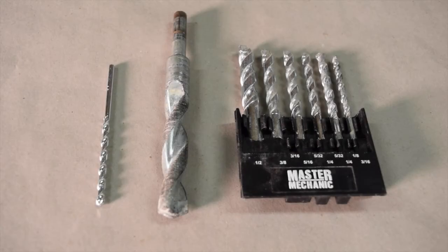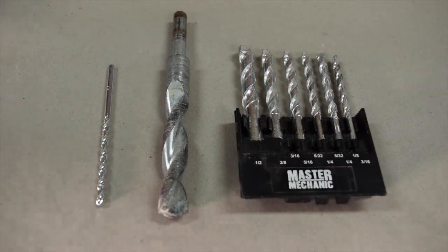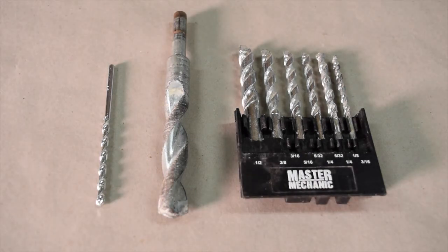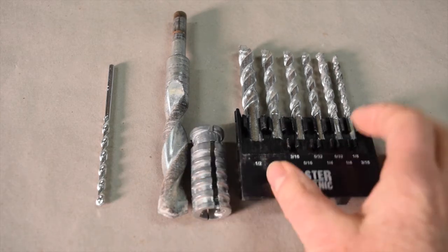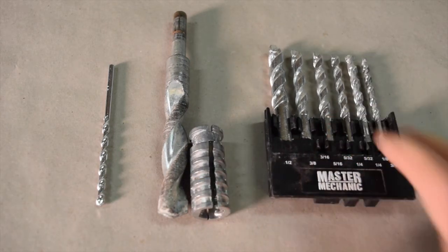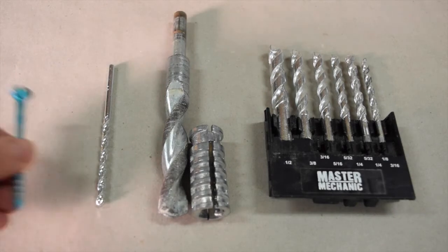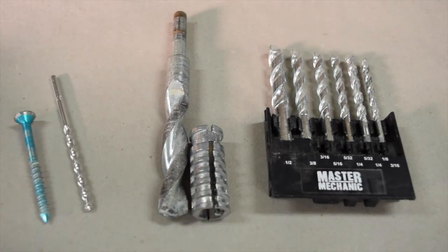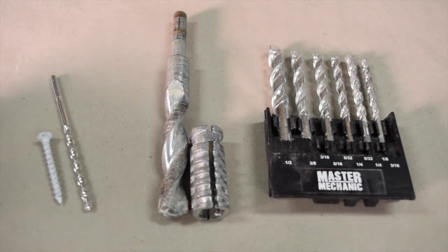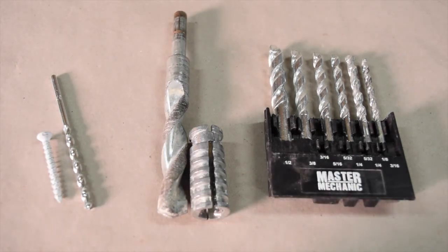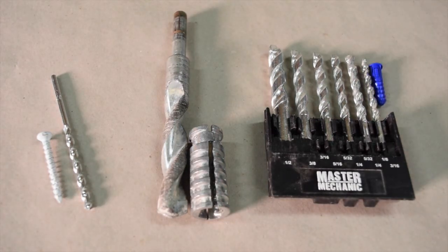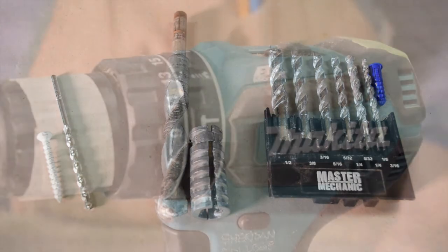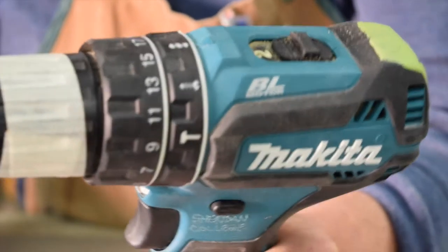When drilling into concrete or brick, you'll need to use a masonry drill bit. It looks similar to a twist drill bit, but you'll notice a difference at the end where the carbide tip has been brazed on. You'll need to size the hole that you drill very carefully, depending on the fastener that you're using. Slightly too big, the fastener will spin. Slightly too small, it just won't go in.